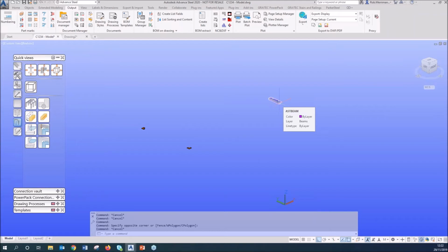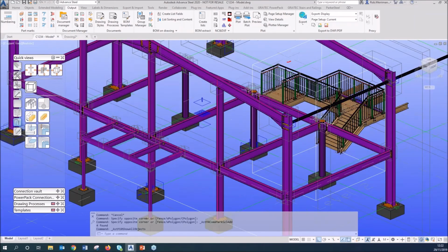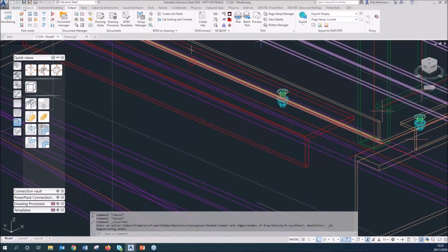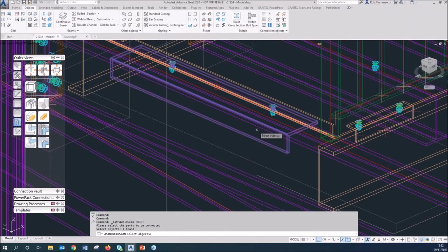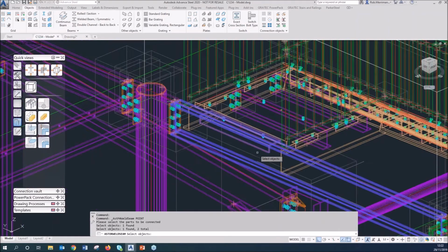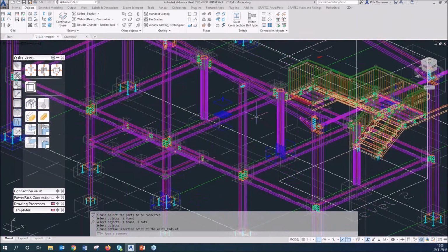Then there's the cost of delaying the installation of the staircase and the columns and the balcony and things like that. So you always want to do all of these checks. I did on every project. So what I'm going to do, I would then come in here, have a look at that and go, right, that should be welded. So to weld something manually, I choose the weld point here, select the two items I want to weld together, and then I'm just going to say, well, we're going to put the weld in there.